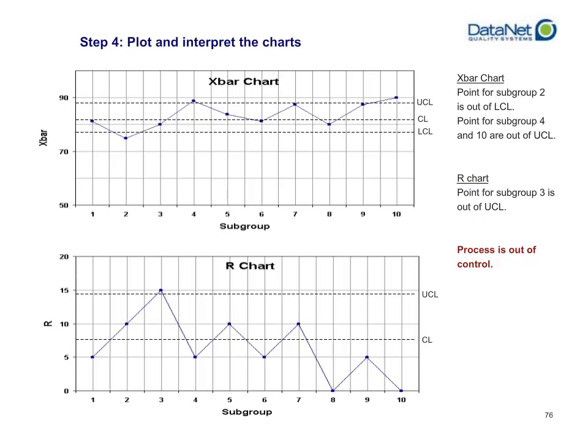Because while you are producing a product that has no variation within the individual subgroups, the last subgroup value that you plotted was also equaling your upper specification limit. And that's something that you didn't even plot here. You don't really need to plot spec limits when you're doing SPC. That's not the function. The function is first to get you into statistical control, meaning to get you into a state where you are stable and your process is not shifting, which this process clearly is. But afterwards, then you can begin to look at what's going on. Why are you now straddling the upper spec limit?